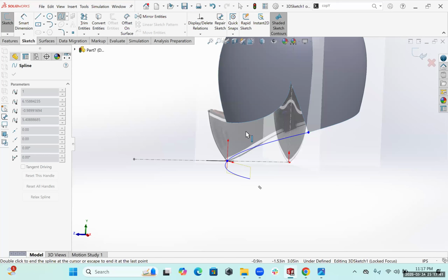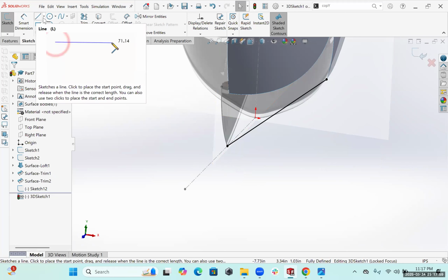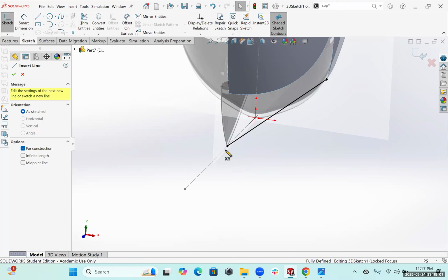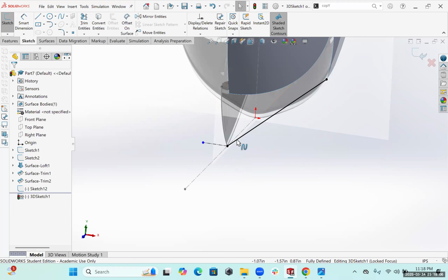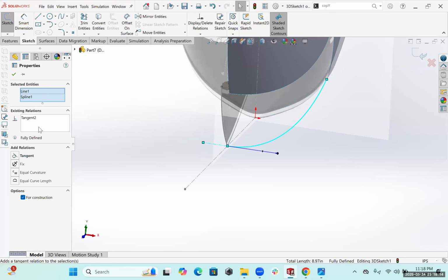Okay. So now that we're looking at this in 3D, we know this portion needs to be mirrored. Therefore, we need to make sure this is coming out straight, so when we mirror it, we don't have a weird line here. So we need to set that to be curvature continuous to a horizontal. I'm using my center line to create this horizontal, and I'm gonna give a parameter of equal curvature. Actually, down the tangency. I'm gonna do C equal.